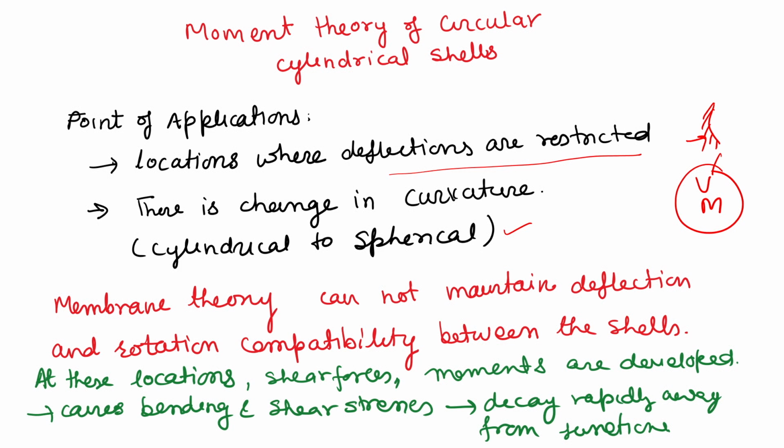But a very important observation, a point to be noted, is that at the junctions, though the moments, shear forces, bending stresses and shear stresses are generated, they decay, they vanish very rapidly when we go away from that corner or joint.